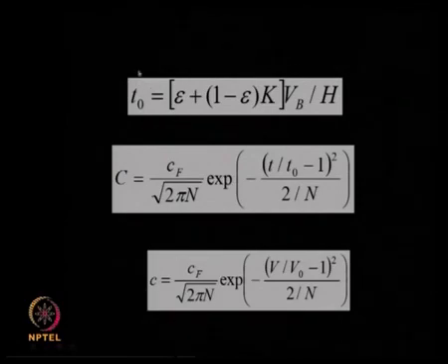And then t naught, that is the elution time, that is the time at which the peak is maximum, is related to your voidage, it is related to your linear adsorption isotherm term K, volume of the bed and height of the bed, okay, in this fashion.